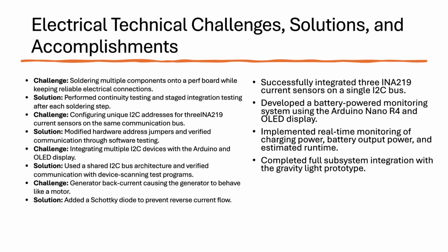Throughout this project, we faced many challenges. One of the biggest challenges we faced was integrating multiple sensors and devices onto the same Arduino while maintaining a reliable communication and electrical connection. This required soldering components onto a perf board, configuring unique I2C addresses for each current sensor, and troubleshooting communication issues between the sensors and the OLED display.